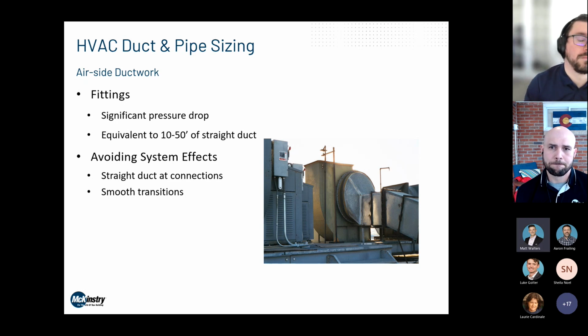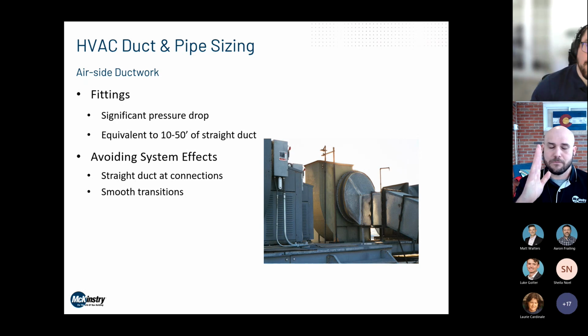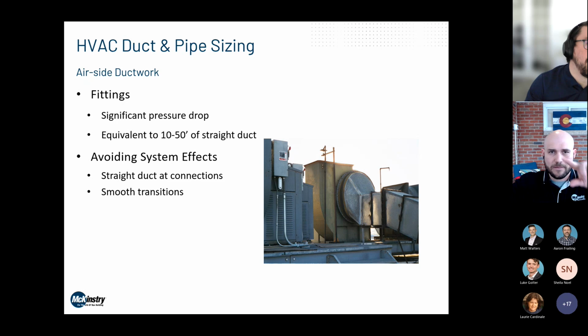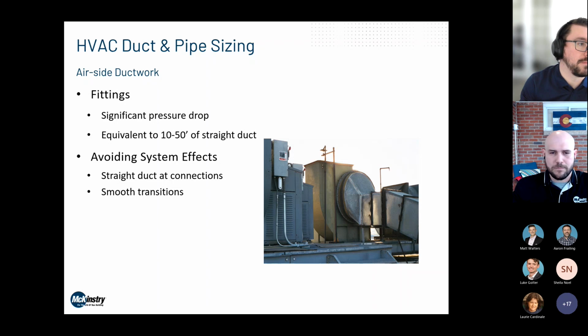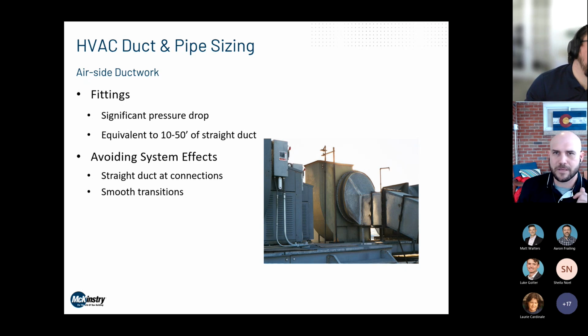And do certain types of fittings have significant effects on the noise? Yes, like a bullheaded T where you have air going into something and then teeing into both directions. Those are particularly noisy. There are things that can be done to help reduce that, like elbow turning vanes in the elbows, or a divider to split if it's not an even 50-50 split between those two. And you could go with a different arrangement of ductwork fittings to try and avoid having a bullhead T like that.